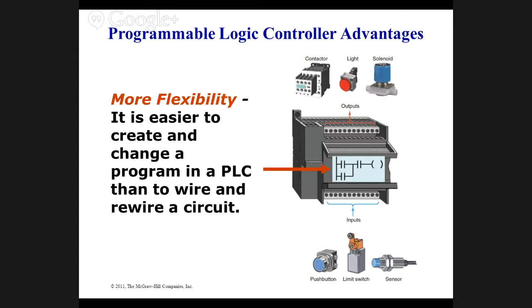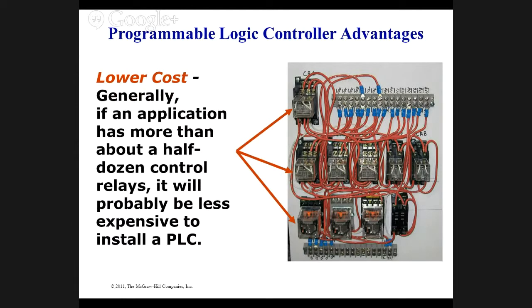Let's go on to the next one. Low cost. Well, let me tell you something about PLCs now. You can buy a Rockwell programmable relay for $80 that has 4 outputs and 4 inputs, and the software is free. And there are other brands. Well, if you went and bought an Allen Bradley relay base, one of these relay bases, that would be $80. So basically, it is a quarter or a fifth the price of buying 4 of these, right? All these wires and relays would cost more than a small little PLC. You with me so far?